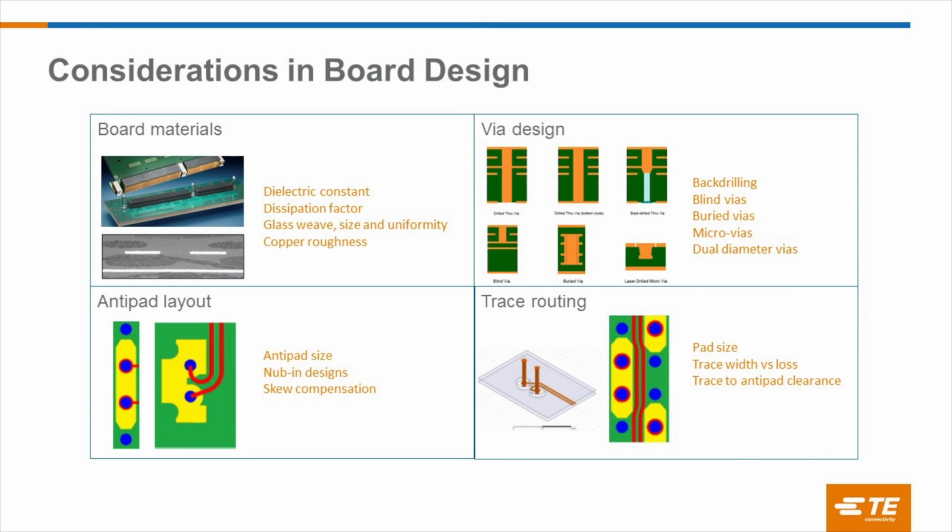VITA 68 is looking at all those elements and where that budget will be. For higher data rates, if you have a 10 gig plug-in card or multiple 10 gig plug-in cards, they will be compliant with any 10 gig backplane. We need to make sure that that interoperability stays valid at those higher speeds.